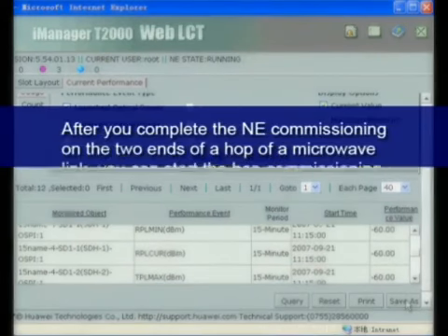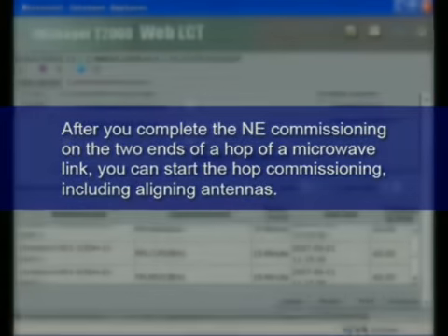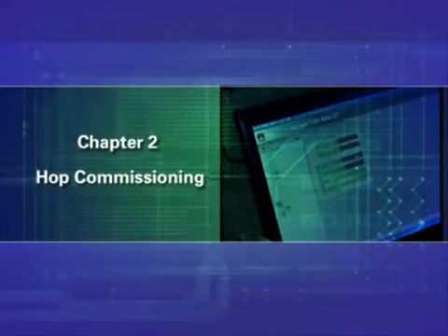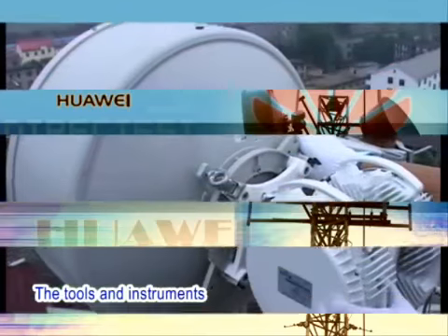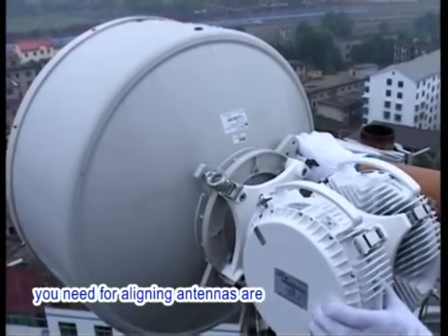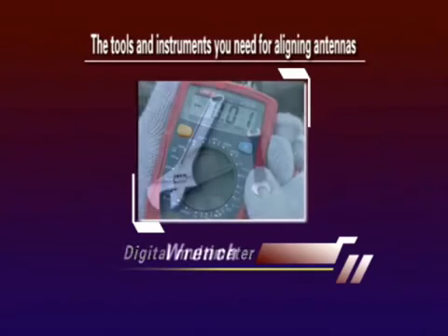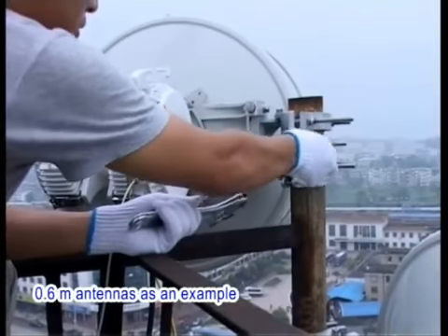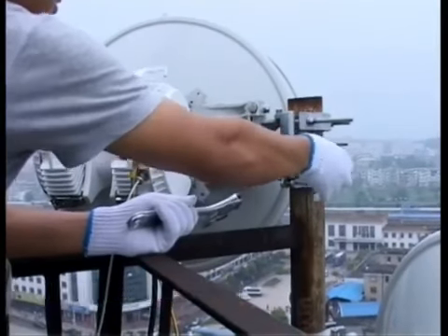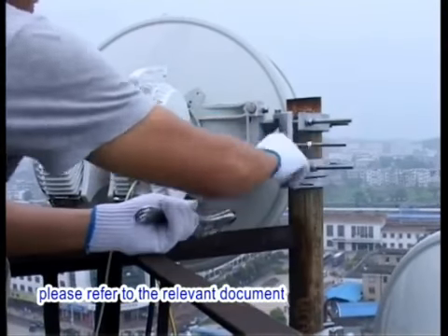After you complete the commissioning on the two ends of a hop of a microwave link, you can start the hop commissioning, including aligning antennas. Chapter 2. Hop Commissioning. 1. Aligning the antennas. The tools and instruments you need for aligning antennas are BNC cables, digital multimeter, and wrench. The following operation considers aligning 0.6 meter antennas as an example. When the antenna is of a different diameter, please refer to the relevant document.